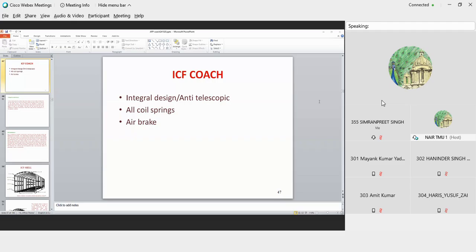Railbus uses DEMU technology. You see, different rail buses use different technologies, like some are very rudimentary. We have also fitted a truck kind of a cardan shaft and an axle drive. DEMU technology is generally defined where the engine is more powerful and it can carry 3-4 coaches. We have converted these rail buses with something called diesel hydraulic multiple unit technology, where we are using hydraulics in the transmission system.